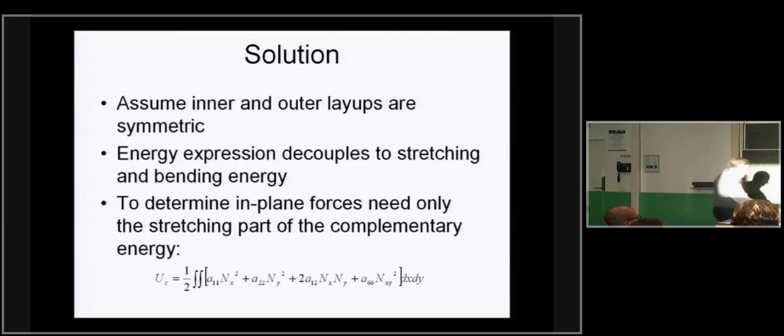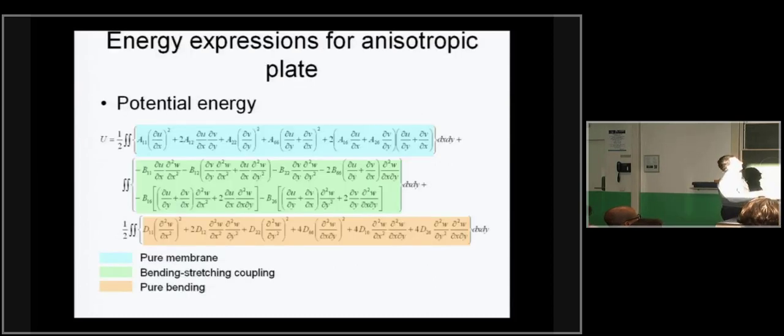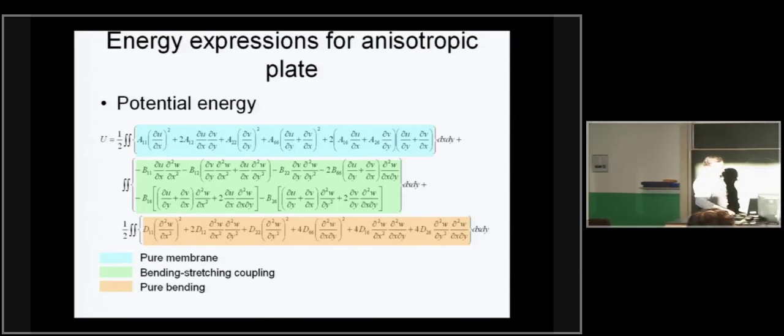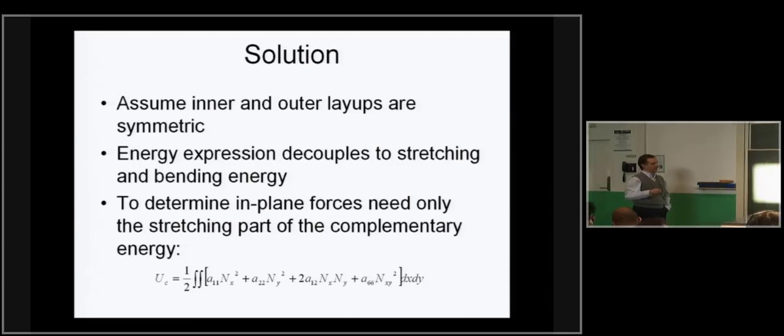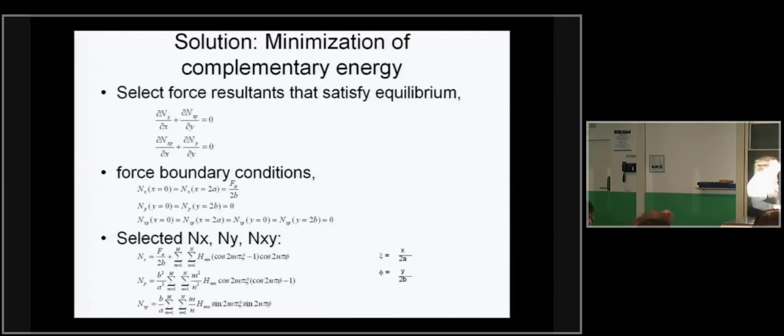For the buckling check, you would need the D matrix also. Instead of the expression I showed earlier, which would require displacement based, you would need the top equation here, or the top line, which involves the A matrix, and that's the displacement based energy minimization approach. If you do a stress based or force based, then the exact equivalent, instead of involving the A matrix, involves the little a matrix, which is the inverse of it, and it has this expression here. Notice there is no A16 and A26 because we are assuming that there is no stretching shearing coupling, so the capital A16 and A26 are 0, which means when you invert it, the little a16 and a26 are 0.